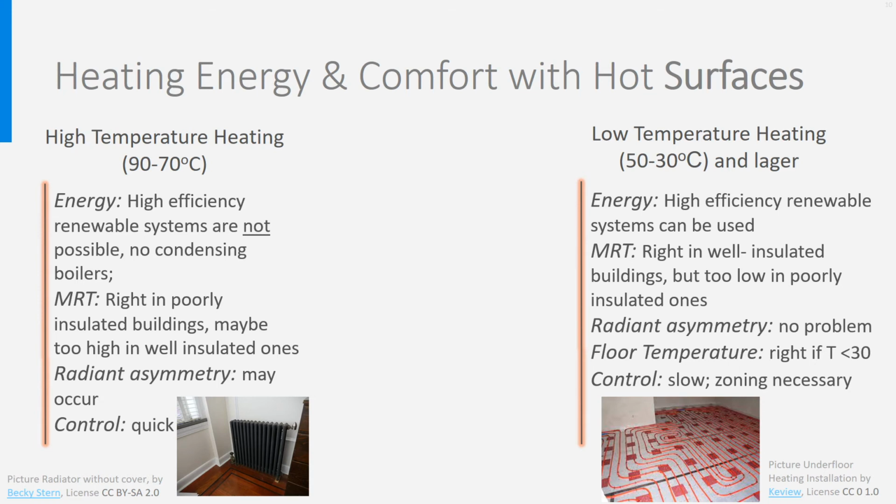As for floor covering, almost all materials can be used nowadays. Most producers offer variants of their product optimized for floor heating, that is having a high thermal conductivity, but always keep the allowed floor temperature of the product in mind.